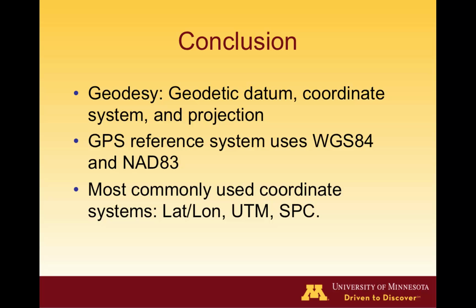However, no matter if the coordinate needs projection or not, no matter if the coordinate system is based on 3D or 2D, it needs a geodetic datum, which is the way to describe the size and shape of Earth. And we know that with different datum, you have different sea level, different average level, and different ways to decide the height on different surfaces, different locations with different surface conditions.